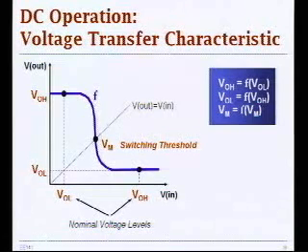So noise sources can be power supply noise, it can be crosstalk in the form of capacitive coupling or inductive coupling, it can be intersymbol interference, it can be timing noise due to clock skew and clock jitter, and so on. And we will analyze these noise sources later on in the semester.